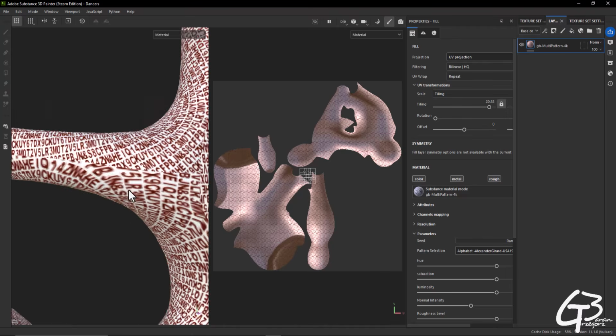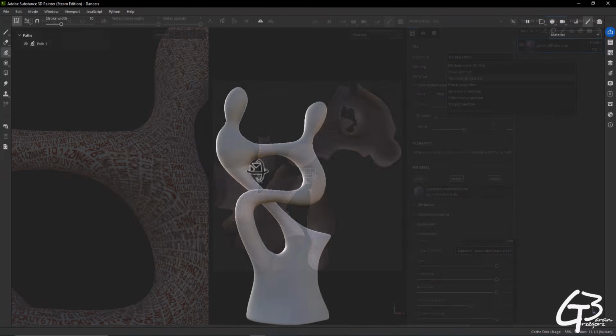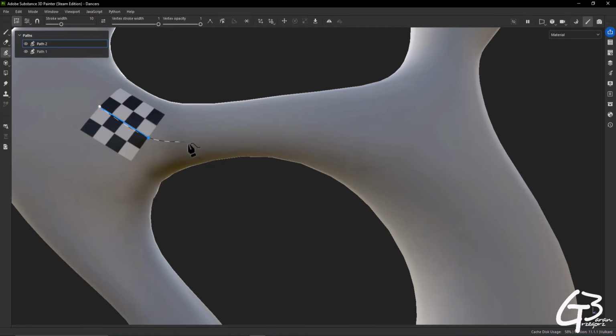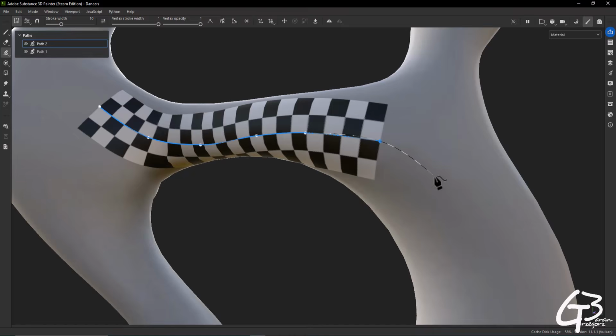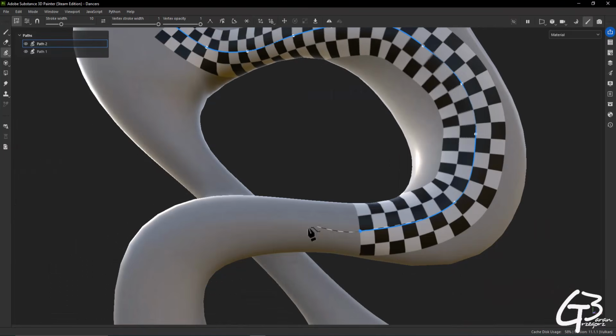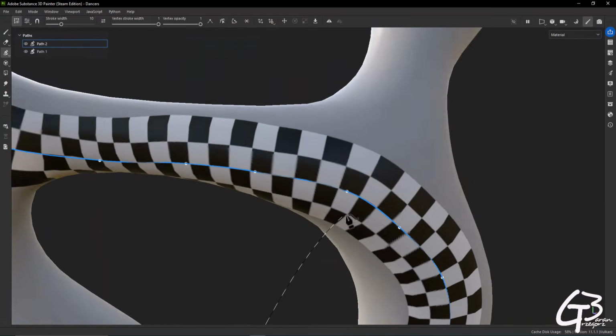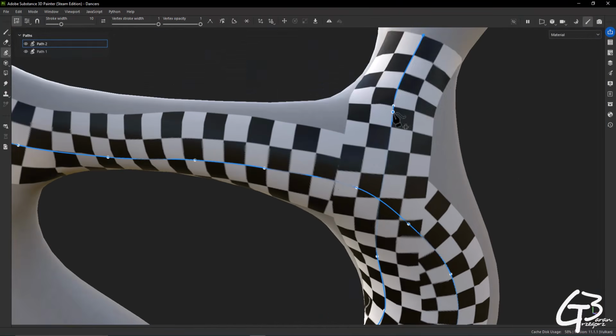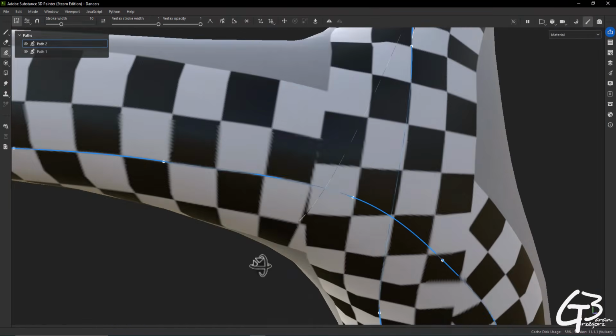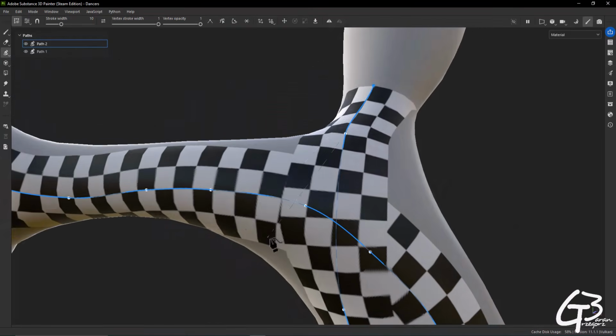Sharp transitions in color or value, like black to white or red to yellow, also make seam stretching and compression much more visible. In these cases, preserving directional integrity may require adding more seams or relaxing island angles, even if it means sacrificing some packing efficiency.